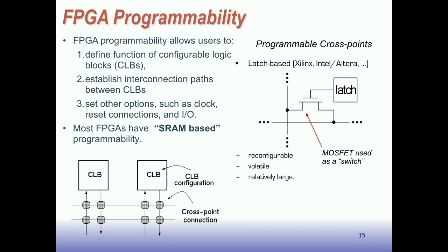Right. So one way to do that is to use, again, a MOSFET, MOS transistor, which can act like a switch, as you recall, hopefully, from another class. So if you put a high voltage of 1 here, this essentially makes a short circuit, a low resistance path between these two wires. If you put a 0 here, it makes an open circuit, a high impedance path, or a high resistance path between those two wires, so a signal can't flow between those two paths. So it acts like a switch. So we can turn the switch on and off by what we put in the latch.